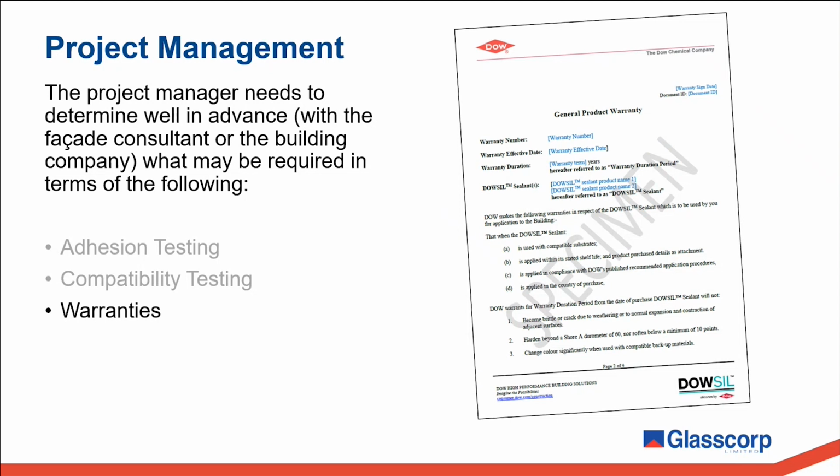And finally, warranties. While not necessarily a common requirement for most projects, particularly for weather and construction seals, they are available to us if required. Because a large part of the ultimate performance of a sealant will depend on workmanship and surface preparation and sealant application, warranties for sealants tend to be issued on a project-specific basis.